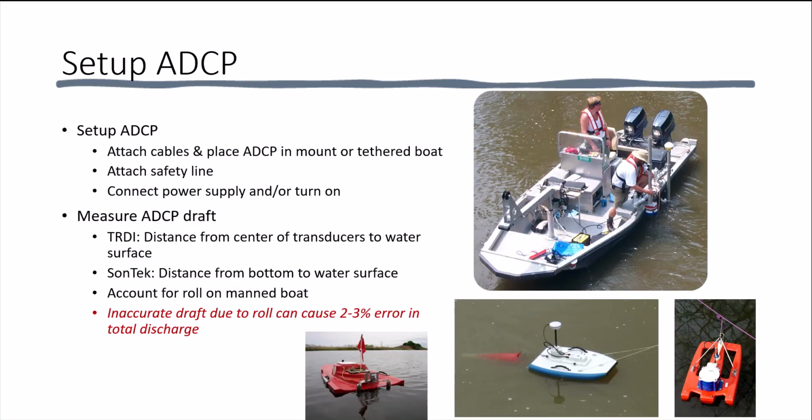At the site, the first step is to set up the ADCP, which will vary based on your deployment method. The ADCP should be mounted and cables or radio modems attached. I always recommend attaching a safety line to the ADCP, both on a manned boat and when using the tethered boat. Once everything is connected, attach the power supply and ensure that the unit is powered.